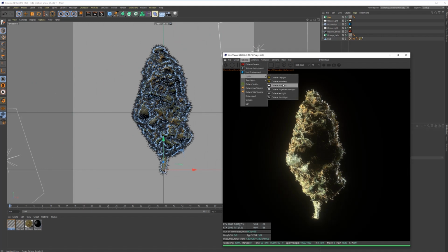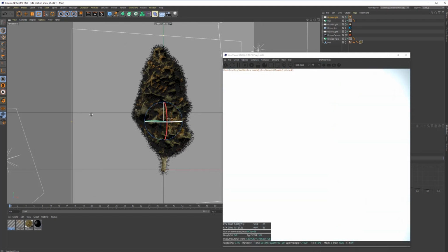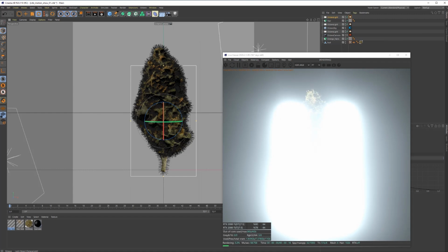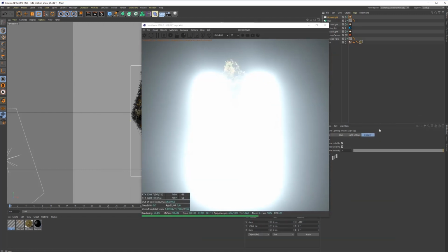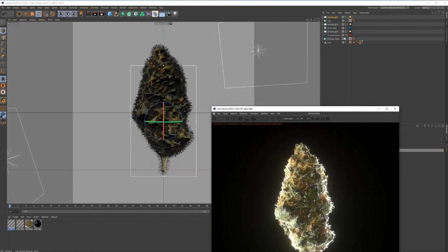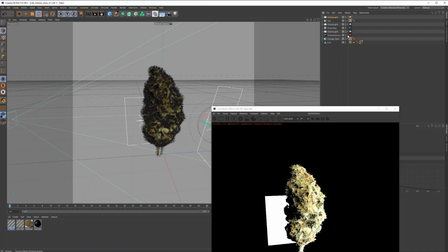All right, let's get another light in here and let's really backlight this object now. Let's rotate this 180 degrees. Obviously it's going to blow out the image. Let's just scale this way down, maybe something like that. Again, I don't want this light to be visible in the camera or anything like that. And now we're going to get this really nice perimeter edge light. Right now though, it is intersecting the geometry, so that's not what I want. So let's pull this back, maybe drop it down slightly and start to rotate this up on an angle.